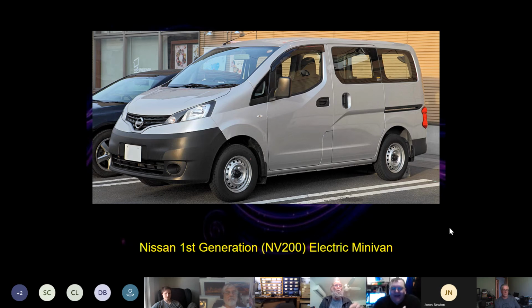Okay. And the reason those batteries are still lead acid is because lithium batteries have a big problem with cold temperatures. Yeah. You get down to freezing and you start to have problems, but a lead acid will still work below zero. Not as well, but it still will. That's why they still use the lead acid batteries. Yeah. And they're cheap, it's very well-defined technology, and it's kind of like, okay, well, it works. It ain't broke, so don't fix it. And they usually don't fail. And if they do, it's usually within the warranty period and you just swap it. Yeah, you just got the 1 in 1,000 batteries and decided to die early. Right.